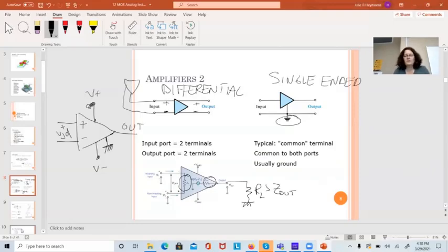In a really precision op amp, that difference between the input terminals is not zero, but it may be 25 microvolts. It's really small. Whereas if you use the 741 like you did in the 188 lab, it probably has a differential voltage around 50 or 100 millivolts. So significant difference in the specifications.